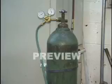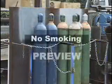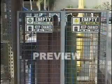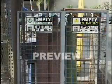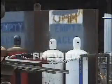Store all cylinders upright and secure them to walls or bench tops during storage or use. Compressed gases should be stored in dry, cool, and well-ventilated areas, protected from the weather and away from flammable materials. The area should be posted for no smoking. Keep compressed gas cylinders, which contain oxygen, away from oil, grease, or liquid flammables. Separate fuel and oxidizing gas cylinders by at least 20 feet or a firewall.